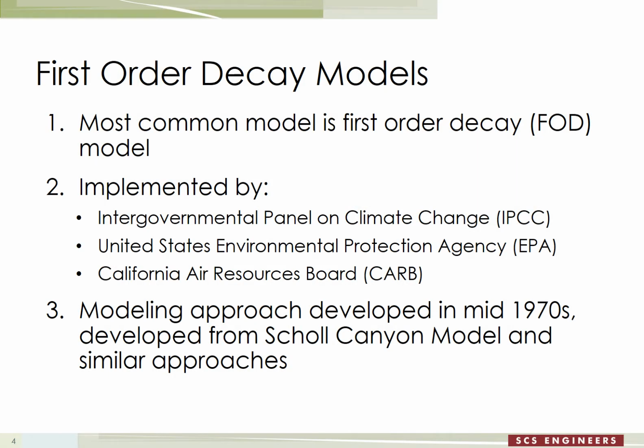The most common model for that is our first order decay model. That's been used for many, many years. There's various versions of that model, including international models. The main model was developed by the U.S. Environmental Protection Agency, which is called the Landfill Gas Emissions Model, or LandGEM, which is probably the most common. And the state of California actually has its own version. It's a bit of a hybrid of the international model. They're all really based on some early work done in the 1970s in a Shoal Canyon landfill in Southern California.